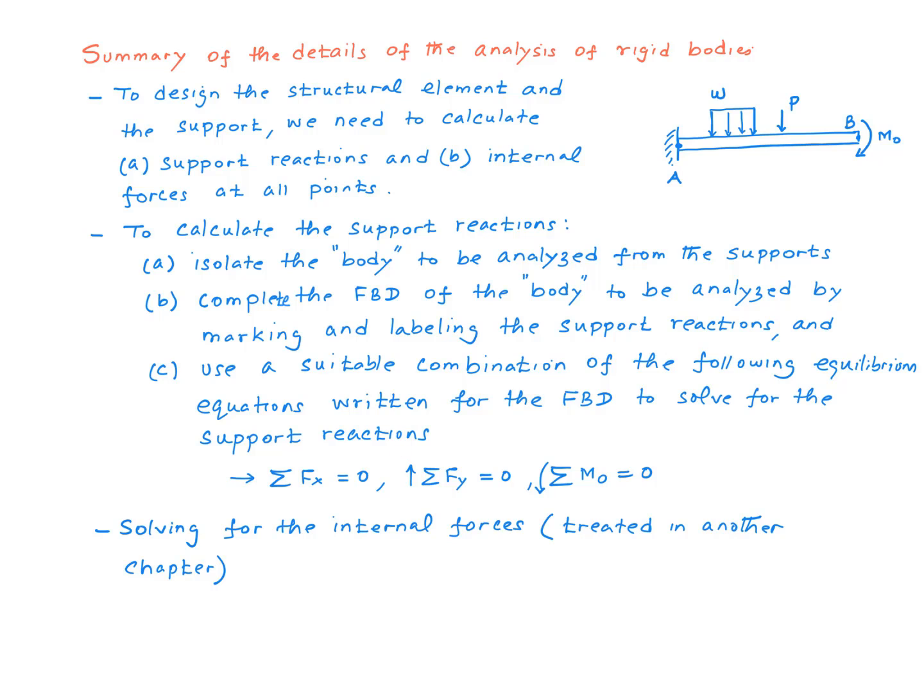Once you have the free body diagram developed for the body to be analyzed, then you use the equilibrium equations to solve for the support reactions. You can use a suitable combination of these three equilibrium equations. As for solving for the internal forces, we'll treat that in another chapter.